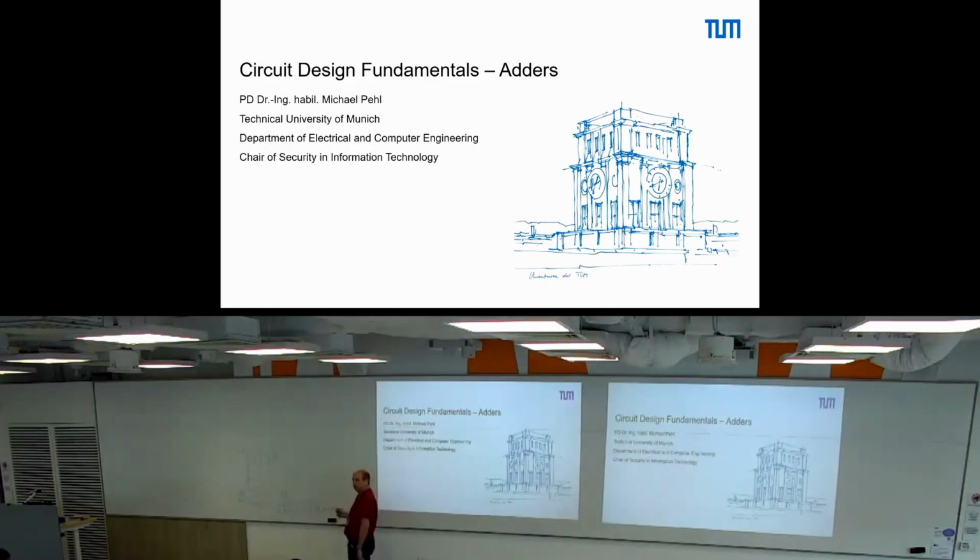Is this an adder? Once again, can this be an adder if we compute our carry like this? No. Why not? The requirement is that we do the connection from the highest index to the lowest index. In this we can apply some mathematical rules, where we are associative. So it doesn't matter if we first compute these two or whatsoever. The second was we are idempotent. So we can compute the same thing multiple times.